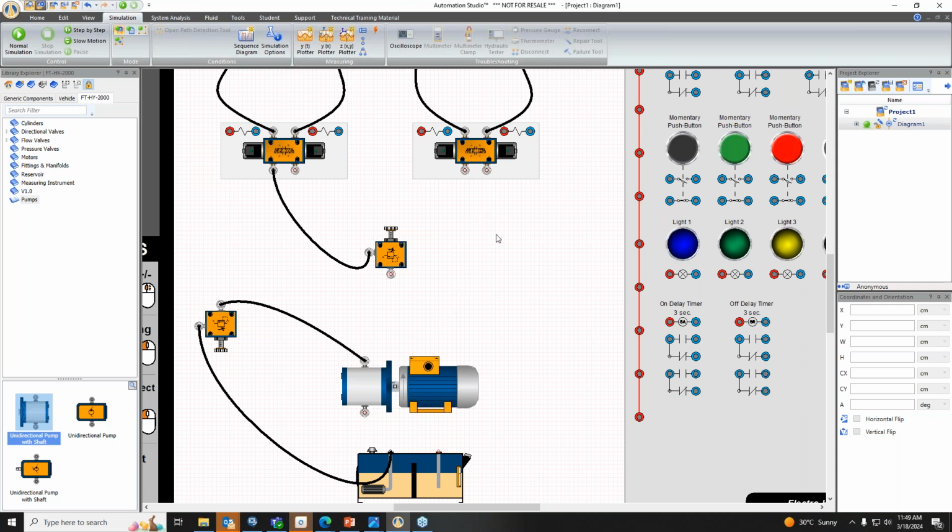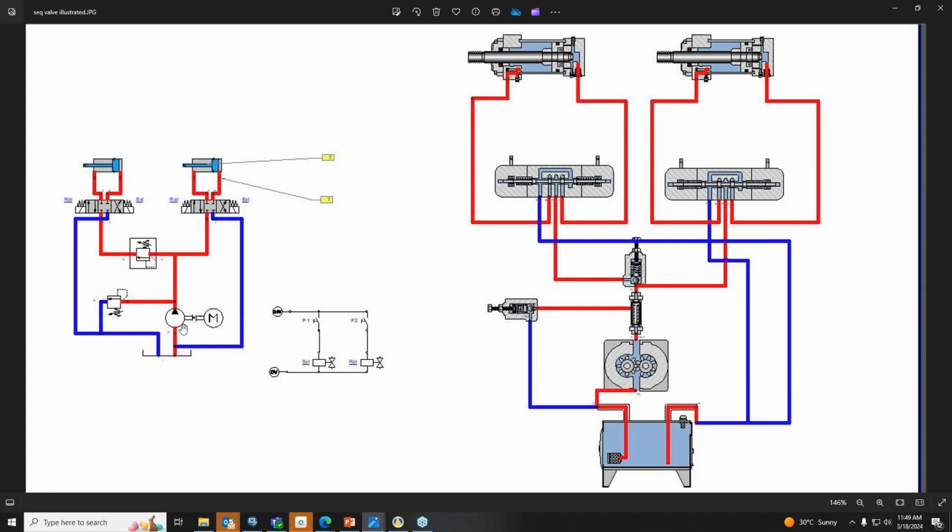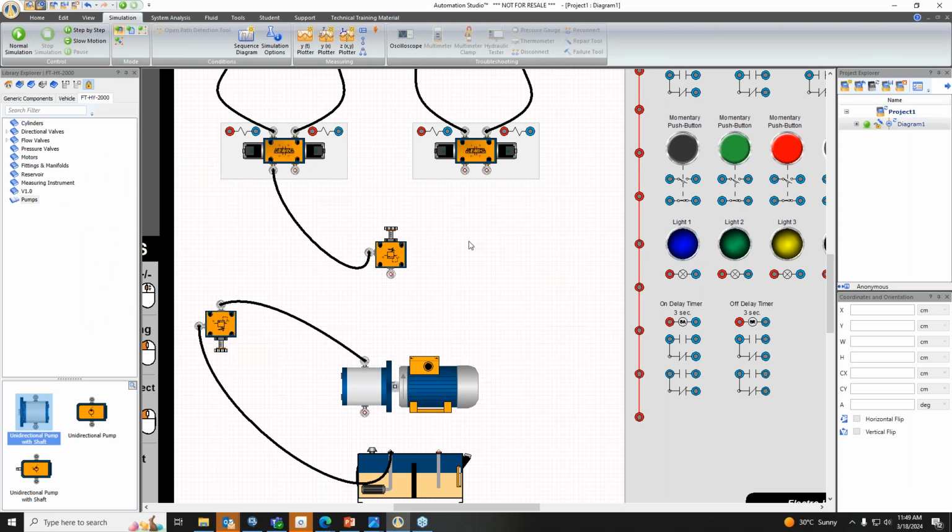the single line. So now for example, if I want to make a connection of the variable relief valve to this DCV, and the same connection I have to make to the pump as well. Because one connection will go to the DCV and the other connection will go to the pump. But here different options will not be available. You cannot simply, like we have done here, double click the lines and then make the connection. Here this will not be possible. So here I have to use fittings. So I'll take a three-way fitting just to make multiple line connections of one component to the other.